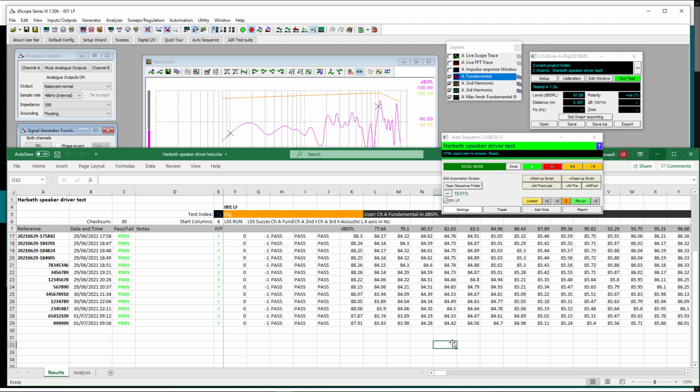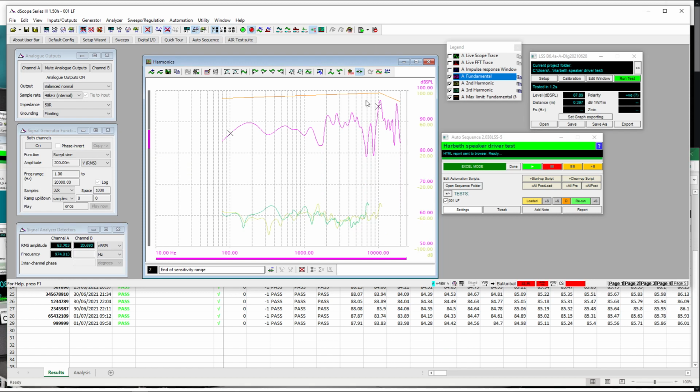So that's a pretty clever way of calculating limits, and in that way you'd be reading your statistically derived limit curve data from your spreadsheet, and you can read it in and set it as a limit curve in dScope. And alternatively, and most easily of all, in fact, you can do a piecewise linear approximation, which is what we have here, a very simple example.